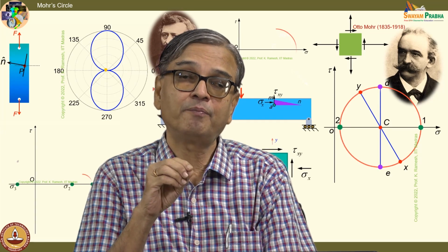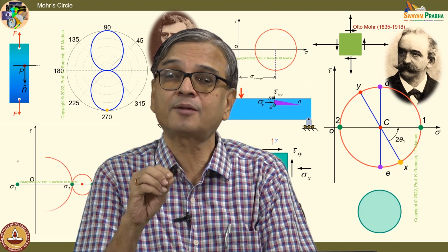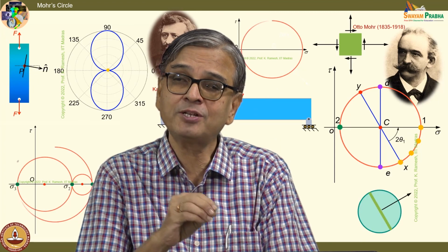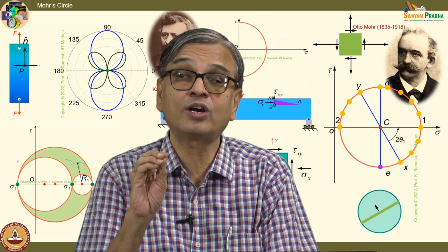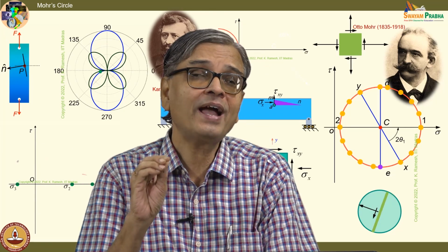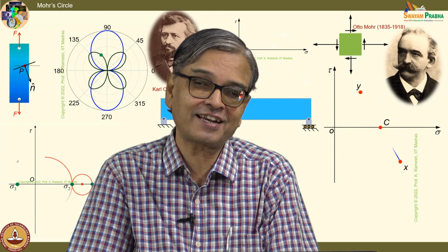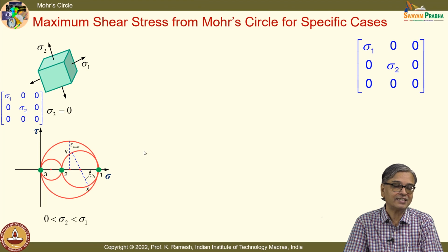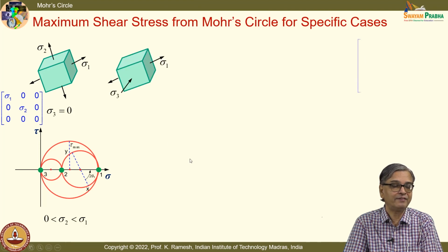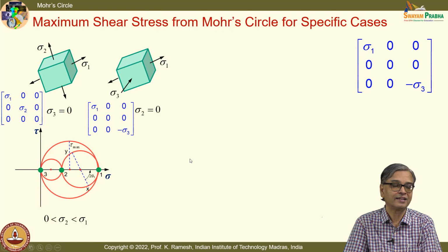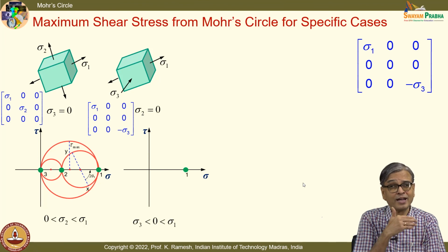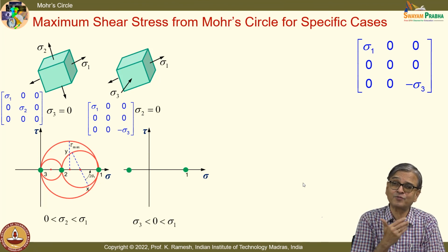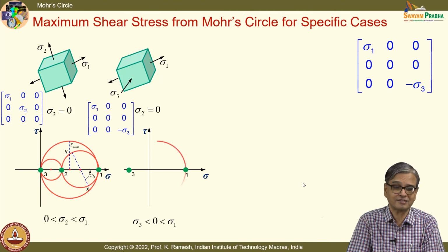This is one of the points where students always make a mistake. When both the principal stresses are positive or both are negative, you have to be alert. In finding the maximum shear stress, go back and think about which plane it is acting in. Even the plane is different. We always want to live in 2 dimensions, but everything is not 2-dimensional. Even in a 2-dimensional problem, you may have to look at a plane in 3 dimensions to worry about the shear stress.